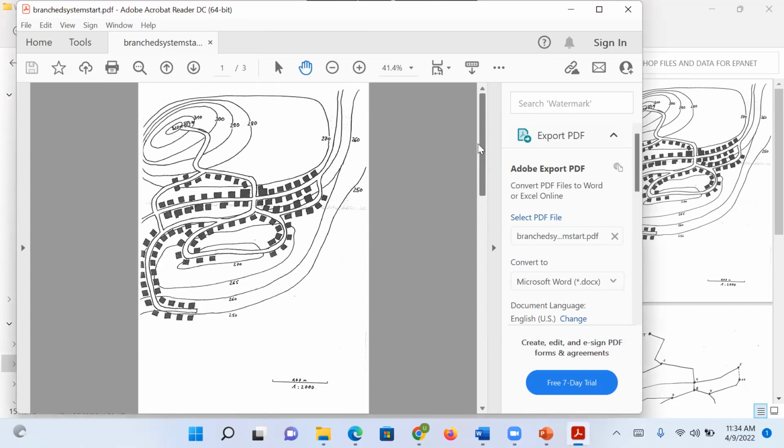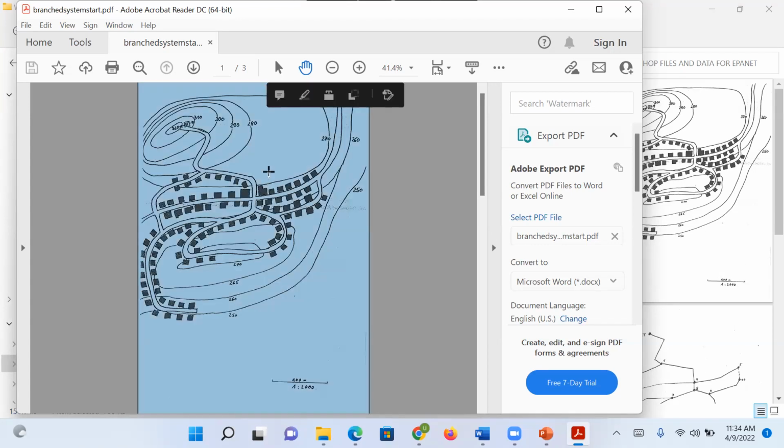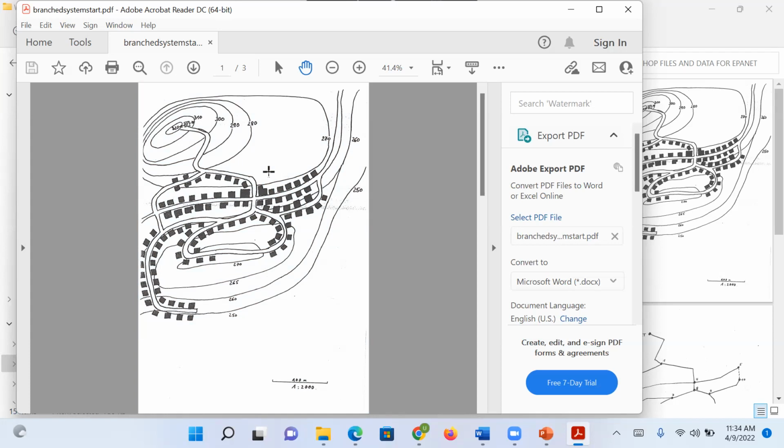Node 5 has, in real sense, in practical sense, some of these things that look bigger than others could be schools, hospital, hotel, industrial complex. So those ones, you treat the water demand not as a flat rate, not as flat as we've been doing. You know, we assume everyone to be the same size, the same prototype, the same type of house, the same number of occupants or standard of living of occupants or whatever. But in real life, that house looks more like a hotel. So I'll go and calculate it separately and add it up.